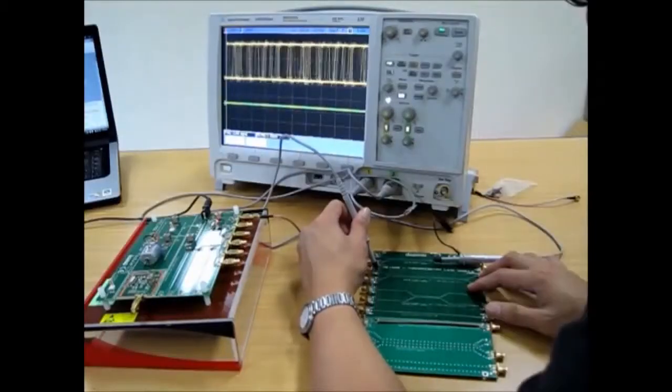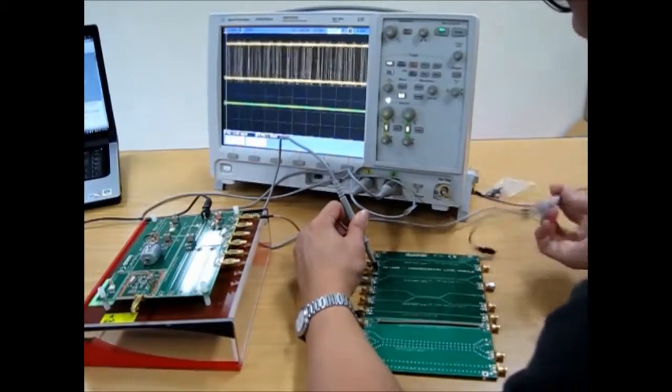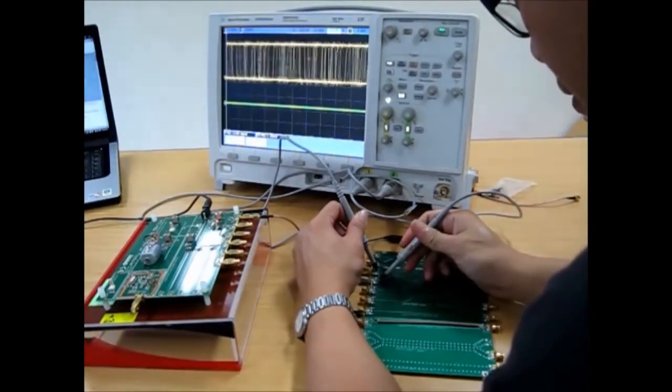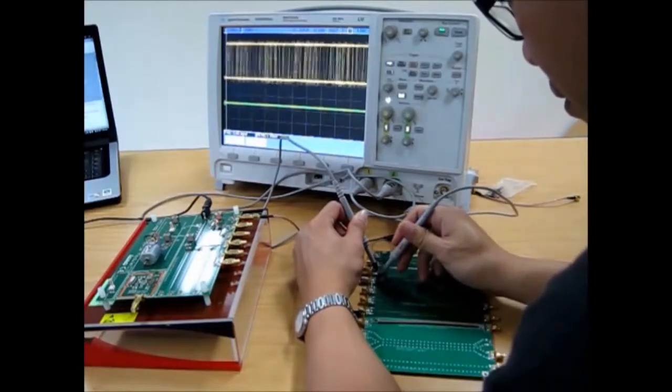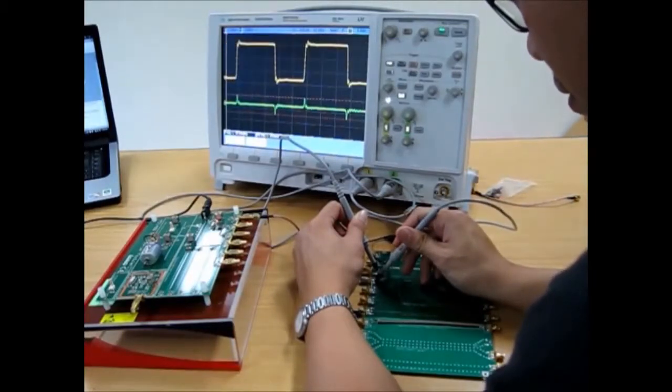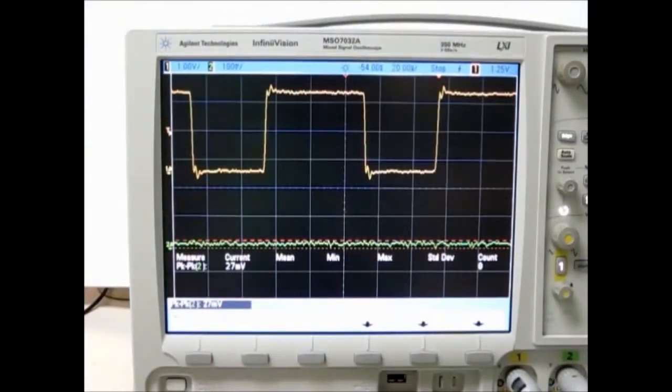From these lab exercises, we can conclude that the spacing and the length of the copper line of two adjacent lines can affect the crosstalk level significantly. So to avoid getting crosstalk interference from adjacent lines that carry high-speed pulses, you need to keep adjacent lines away from the high-speed lines at a sufficient distance.